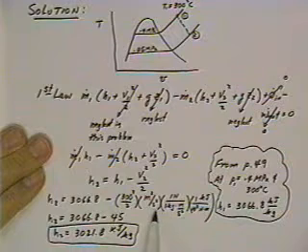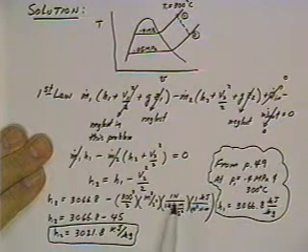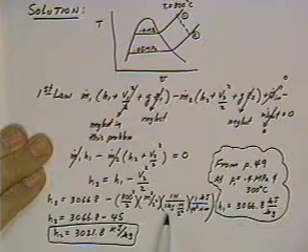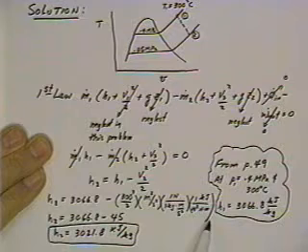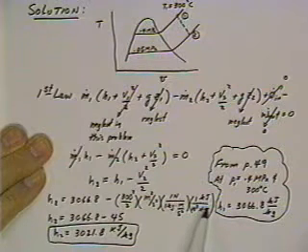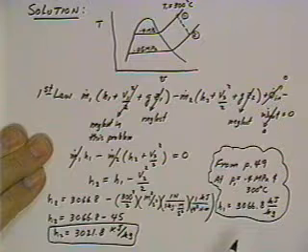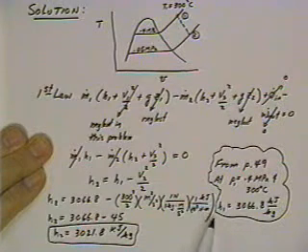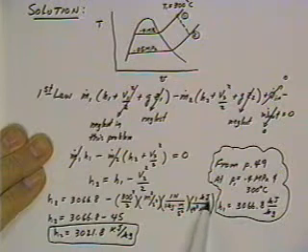That's meters squared per second squared, and then we've got to convert that into the definition of a Newton, which is a kilogram meter per second squared, and then we've got to fill in what the definition of a kilojoule is, and a kilojoule is a Newton meter, and then you've got 1,000 Newton meters per kilojoule.